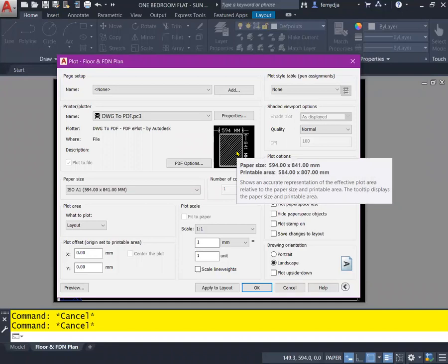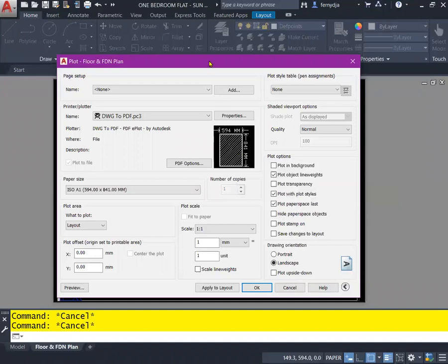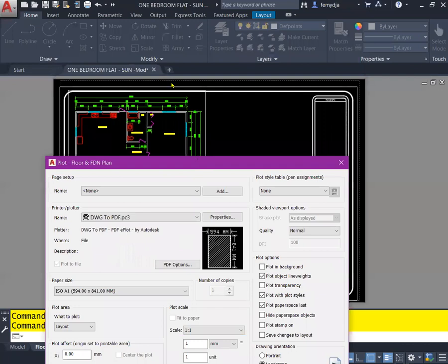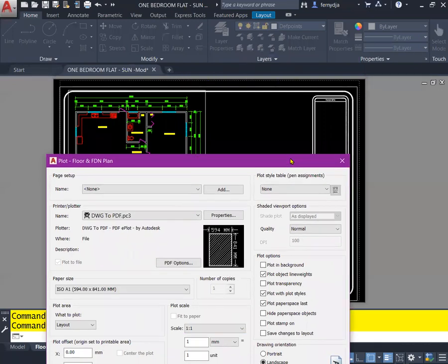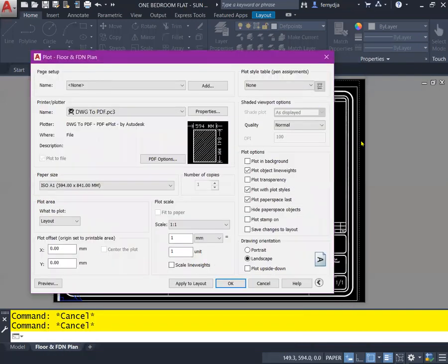So you know you're losing quite a bit of paper there because the margin would have been that dotted line that we would have seen going around the border. By virtue of changing this paper size, it will change the margin. So we want to use one of the full bleed versions that will give us literally no margin. And I'll be able to show you the printable area on that one as well. And you can get your boundary closer to the edge of the paper.